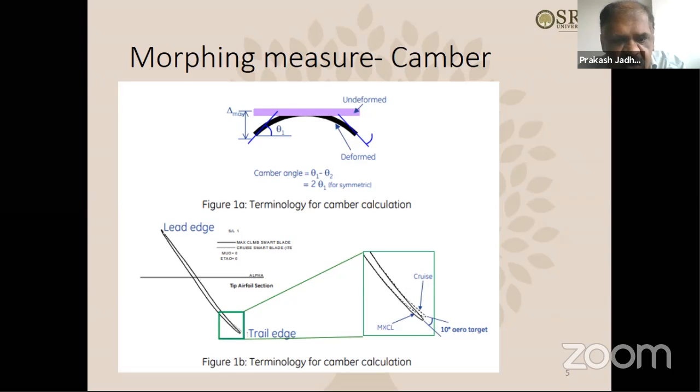So for our composite fan blade, which is used at the front of the aircraft engine, we don't want to move the leading edge, because if you remember, there is a metal cap on the leading edge. So we are left with the trailing edge.